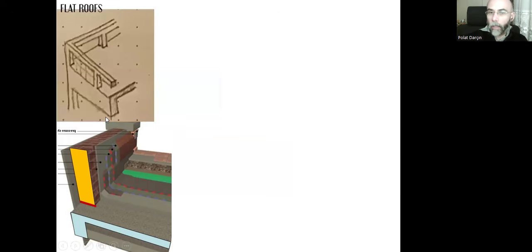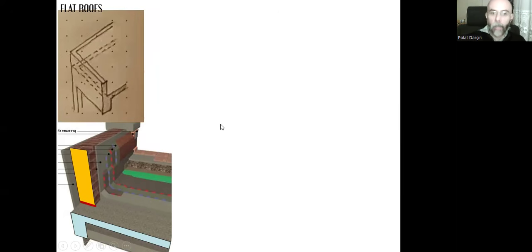That's why we can either prefer brick walls, but instead of fixing them directly over the floor, first we can create tiny columns and beams made out of either reinforced concrete or concrete. With these columns and beams, we are creating a sort of frame where we can place our brick wall, and we will be able to fix the whole brick wall, not only at this one line, but at 4 sides. It will be a better way.